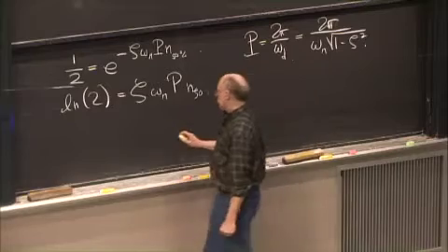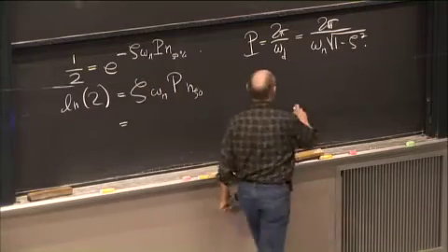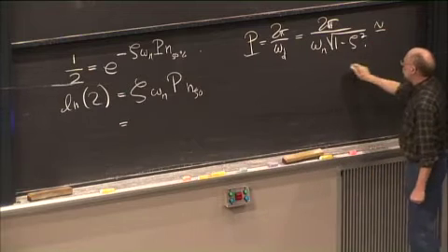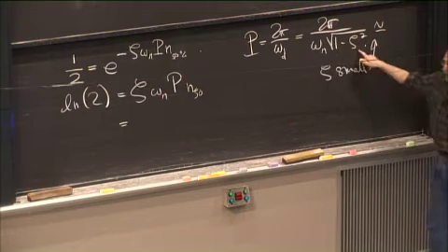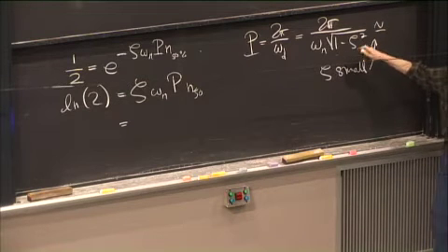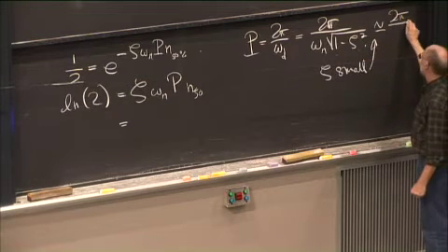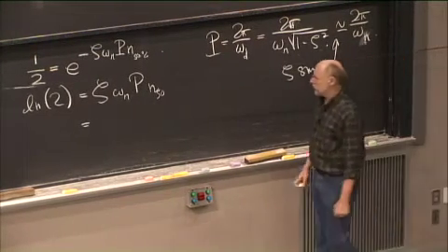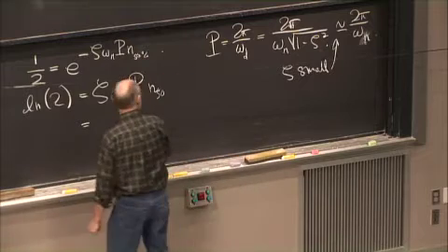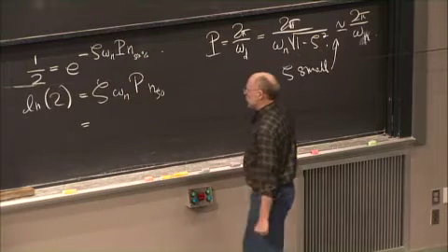So if I put that in here, I will make the approximation that when zeta is small, then 1 minus zeta squared is very close to 1. And so this is very close to 2 pi divided by omega n. In other words, you can replace omega d by omega n in that calculation. So what happens here?